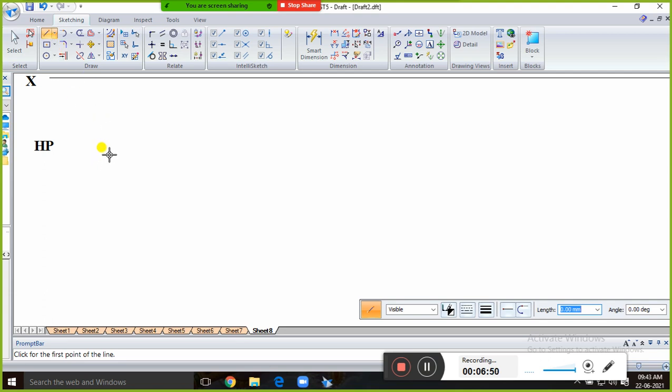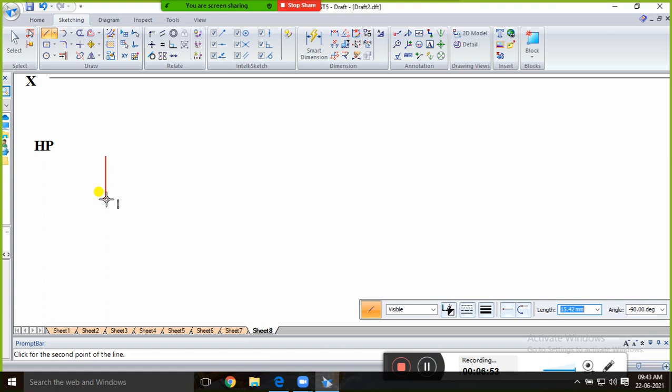So I will show you once again the manual method of construction. First take 25 mm. The length is 25 mm, place it vertically, then place your protractor here, and how much should this angle be? This angle is 90 minus 72, that is the angle. Okay, and the same here, place it here. Okay, and 25 mm the same, and this angle is 90 minus 72, that is 18 degrees, that you have to place.